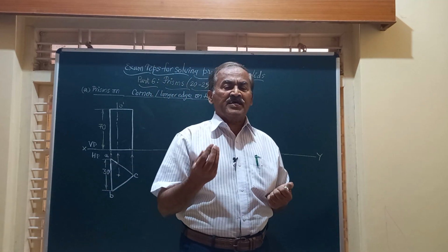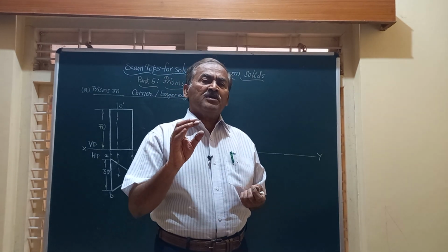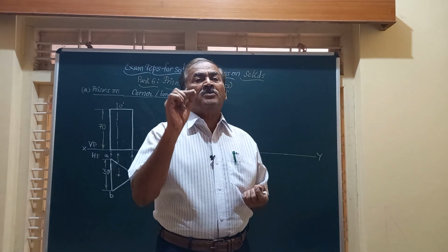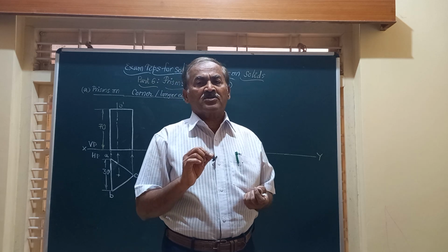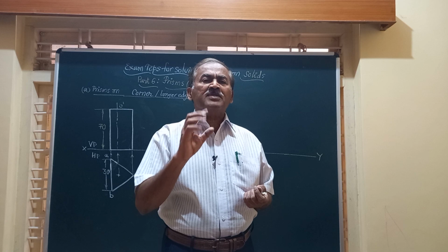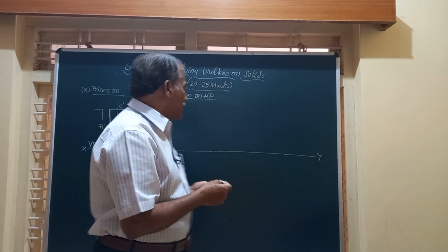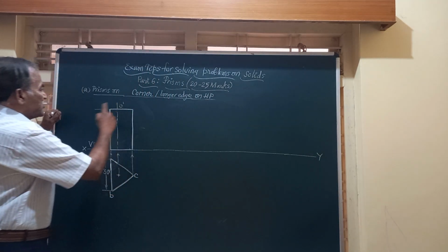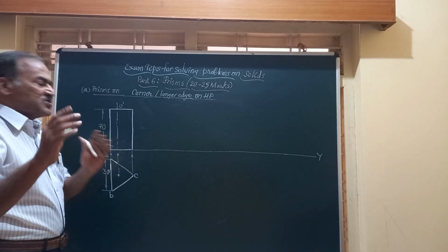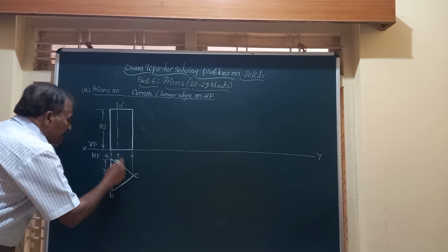have more number of sides like a hexagonal prism or a pentagonal prism, there will be 5 plus 5, 10 points, 2 for the top end and bottom end. There will be 12 corners or 12 points, and if you project all the points together, you will not be able to get the correct front and top views in the second position. So what I do, friends, I have constructed this triangular prism for the given height, and see, marking you should know thoroughly, friends. So I am going to start marking from here, either in the clockwise or anti-clockwise direction.